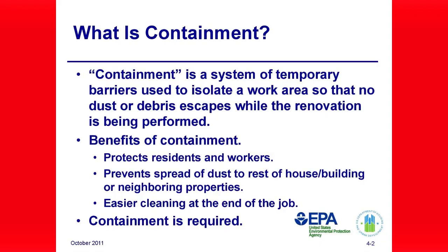Larger areas of disposable plastic sheathing may also be necessary to prevent the spread of dust. Smaller areas of containment may be used if additional precautions such as vertical containment are used to stop the spread of dust and minimize the area of cleanup.